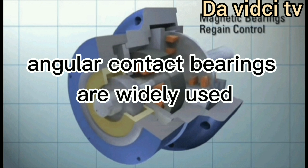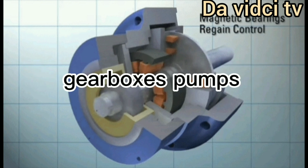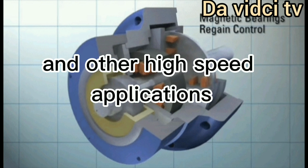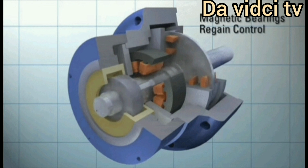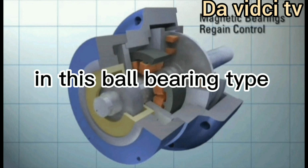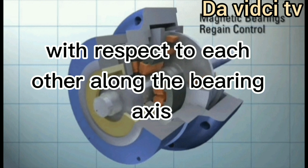Angular contact bearings are widely used in agricultural equipment, automobiles, gearboxes, pumps, and other high-speed applications, such as CNC machining tool spindles. In this ball bearing type, the inner and outer races are displaced with respect to each other along the bearing axis.